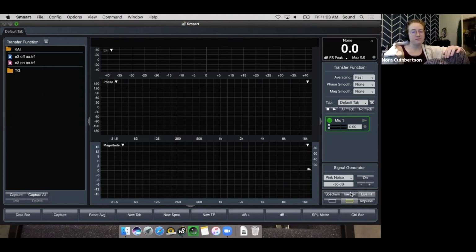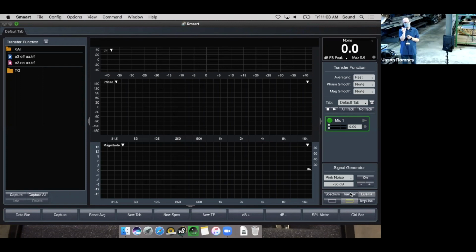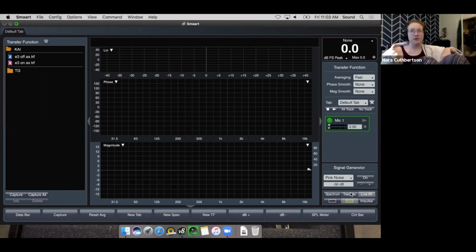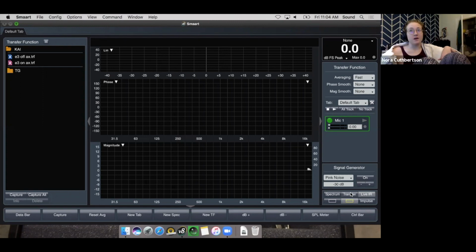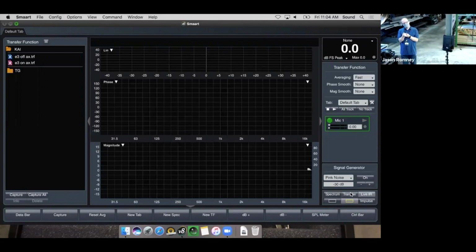Remember when we talked about directivity relative to the size of the diaphragm of a loudspeaker? That you cannot control low frequency. Yeah, so as the wavelength gets bigger than the diaphragm of the driver, that driver starts becoming omnidirectional for that frequency. You keep the diaphragm really small and then they'll all be omnidirectional. Yes, so that is how you make it omnidirectional. One of the other ways you make it omnidirectional is making the diaphragm very small. If you can keep the diaphragm very small, then it stays omnidirectional even at really high frequencies. So like that big studio condenser microphone that has like a 1.5 inch or 1 inch diaphragm capsule on it, it sounds lovely, right?